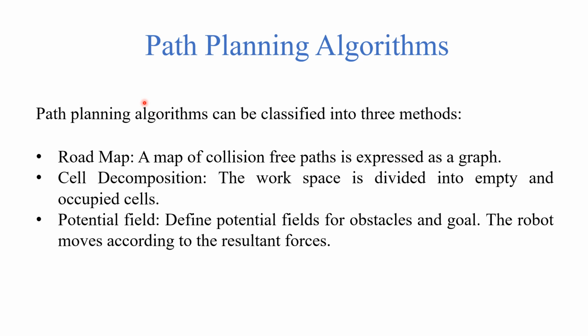In this case, we divide the configuration space into a grid-like representation, in which some cells are occupied, those that intersect with obstacles, and others are free. This creates an approximate representation of the state space with a certain resolution. And then again, we use a graph-based planning algorithm to plan our path from start to goal.